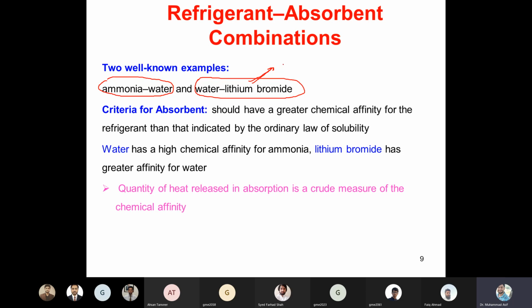When you need to produce chilled water, it is normally 8 to 15 degrees C when we say chilled water. So this chilled water is used for the air conditioning process, as we are doing in the FME or in GIK. In GIK, we are producing cooling through the chilled water. Chilled water from the central HVAC plant is supplied to FME, where we have the air handling unit. There is a room we call the air handling unit. So there is a cooling coil. So the chilled water from the main unit comes into the FME cooling coil.